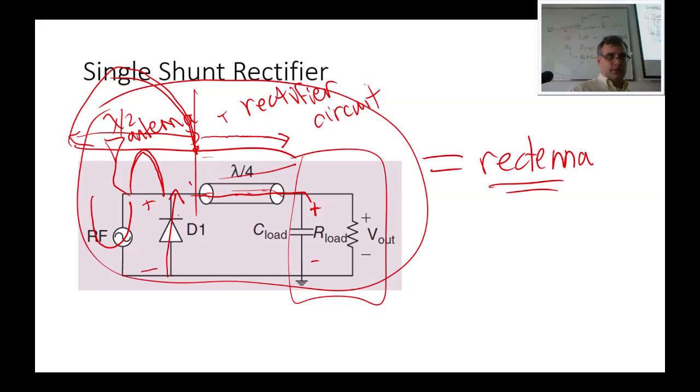It's a short circuit. It accepts charge readily if it's not charged, or if you disturb it. It's only when you make a disturbance and you sit there with that same stimulus for a long time that it charges up and becomes an open circuit. So at DC, this is an open circuit. This is a short circuit.